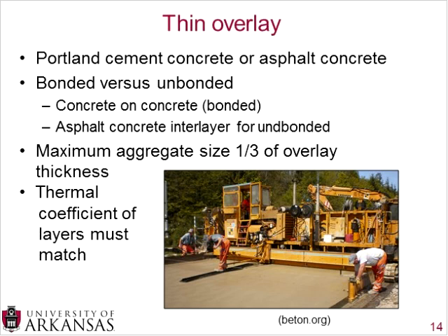The next type of treatment we'll talk about is thin overlays. A thin overlay is where you have an existing Portland cement concrete road. Generally, they're not rubbleized, but they do have a significant amount of distresses where other options aren't quite as attractive. The thin overlay can either be Portland cement concrete or asphalt concrete, and there's some terms that they use to differentiate what type they are. You can have bonded versus unbonded. And generally when a concrete overlay is placed on an existing concrete pavement, that's called a bonded overlay.